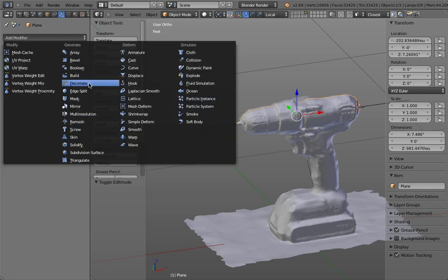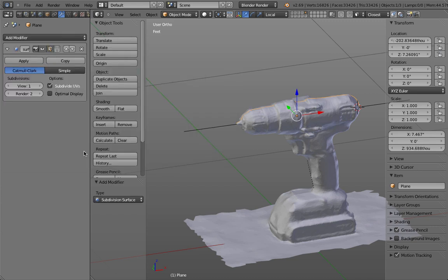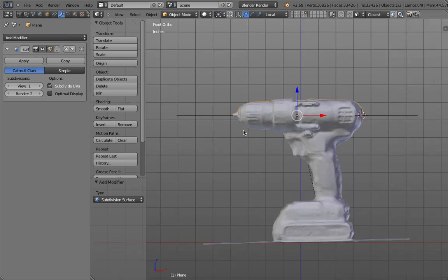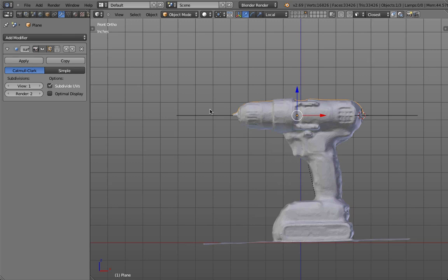So we have to simplify the design a little bit. So it's not about being accurate in terms of how pieces later will be put into the injection mold, but more about how can we create a model that can be 3D printed, and at the same time then later gives us the flexibility to also create manufacturing models from it.